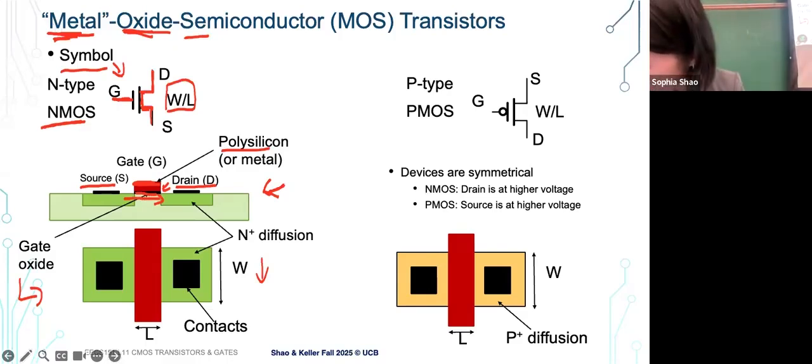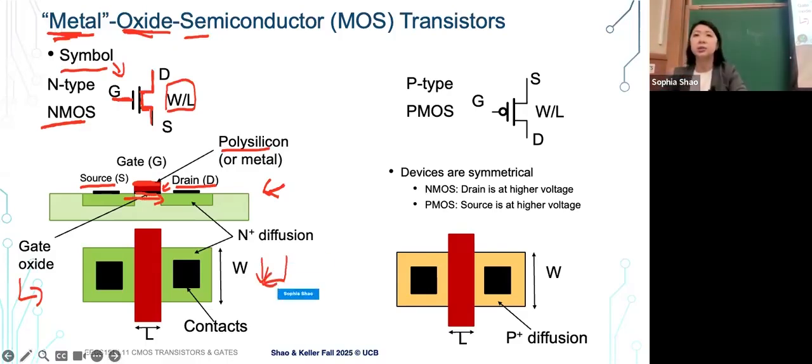When we look at this, it's easier to look at it this way. When we think about a transistor, there are also the dimensions of the conducting layers, right? So here we talk about the length of the channel, which is basically the width of the gate, right? How wide that gate is. For a while, when we talked about semiconductor technology node, it was actually referring to the length of the gate, how wide it is, right? It's getting smaller and smaller.